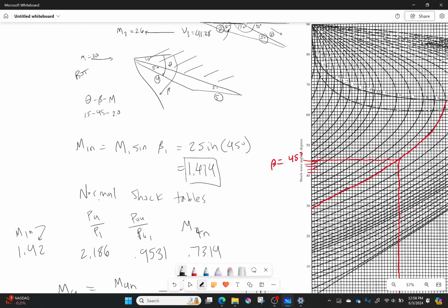So remember, we just did section 4. Now we have to do section 5. And so finally we get to answer the question, is that going to be a shock wave or an expansion fan? And it's got a really super easy answer. The answer is it's an expansion fan. How do I know that? I know that because the flow is already going this direction and it has to then turn and expand. It's turning away from itself, and so it's going to be an expansion fan right there.